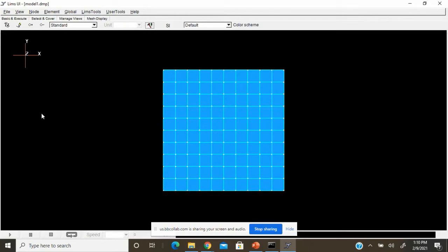Now the main process of running a mold filling simulation is going to be just the first three steps, which have to be followed to the T. The first step for us is going to be assigning where the input of the resin is going to be, and the output of the resin is going to be. In this case, I'm going to just give the input and assume it's going to be the vacuum conditions, as absolute perfect vacuum conditions at the boundary.